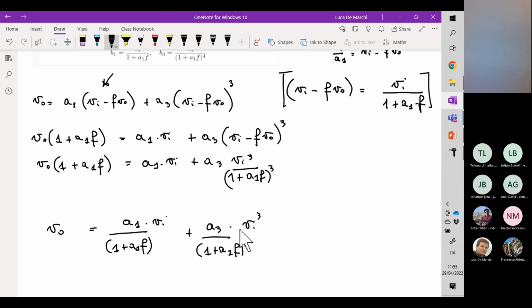So let's say 1 decade after the pole position, more or less, we have already lost 90 degrees in terms of phase. Some more considerations. We have discussed the fact that we are interested in analyzing T of S, the loop gain, so the multiplication of A of S times F.